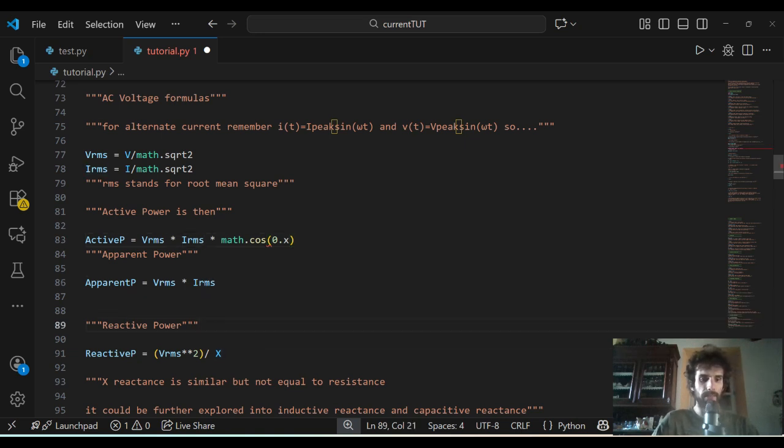We can take the tension raised to the power of 2 and divide it by the resistance. Anyway, the apparent power is the sum of the two and is just the multiplication of the tension and the current. A little reminder on active power and reactive power: the motors that have to spin a lot probably require more reactive power than active power.